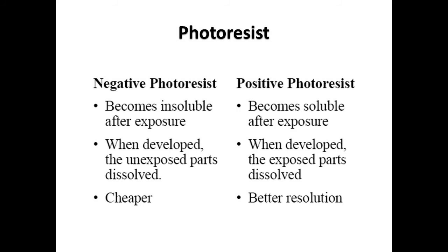For negative photoresist, what are the characteristics? It becomes insoluble after exposure. So after being exposed, it becomes insoluble. When developed, the unexposed parts will be dissolved, and it's cheaper. My tip, if this question comes out, is to first remember that it is a cheaper type of photoresist.